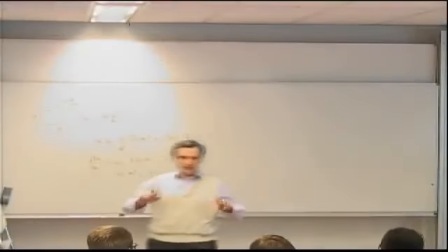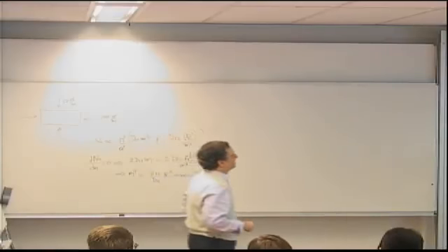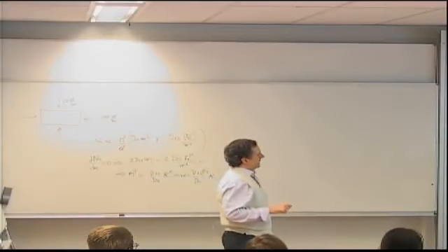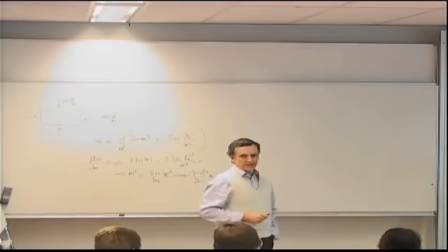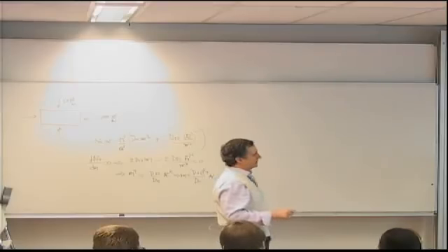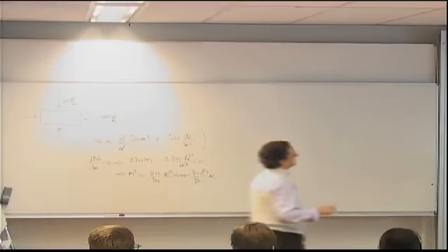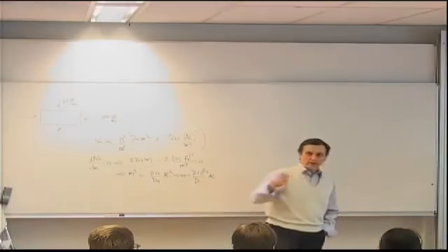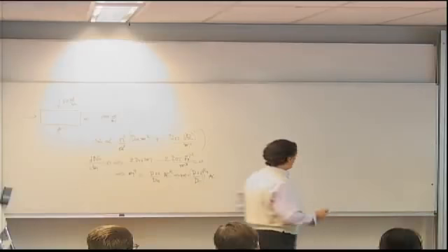So we saw the simply supported case all around under compression as a special case, or under biaxial loading. Now we do this weird case which says I have a plate under compression. Three sides are simply supported and one side is free. Free means that it can do anything it wants. And the free side is not one of the loaded sides. So the free side is not this one or that one. Now why do I do this?